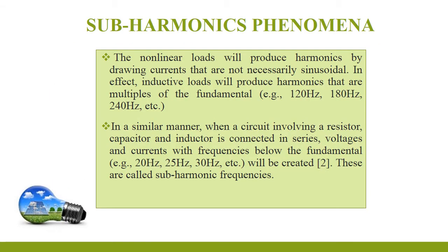Subharmonics phenomena. Nonlinear loads will produce harmonics by drawing current that is not necessarily sinusoidal. In effect, inductive loads will produce harmonics that are multiples of the fundamental. In a similar manner, when a circuit involving a resistor, capacitor and inductor is connected in series, voltages and currents with frequencies below the fundamental will be created. These are called subharmonic frequencies.